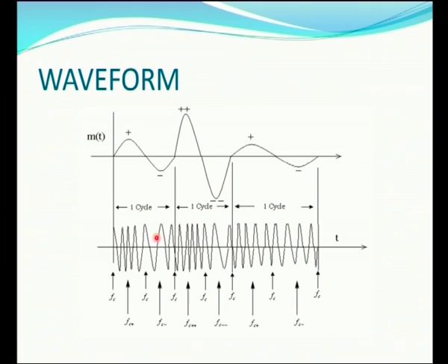Like that you have to vary your applied voltage value, and you will get another peak to peak signal. For this peak to peak signal also you can draw the waveform with respect to the changes in amplitude; the frequency of the modulated signal changes. So, like this you can observe your waveforms, tabulate the readings and get different values of modulation index beta and the bandwidth. This completes your FM modulation.